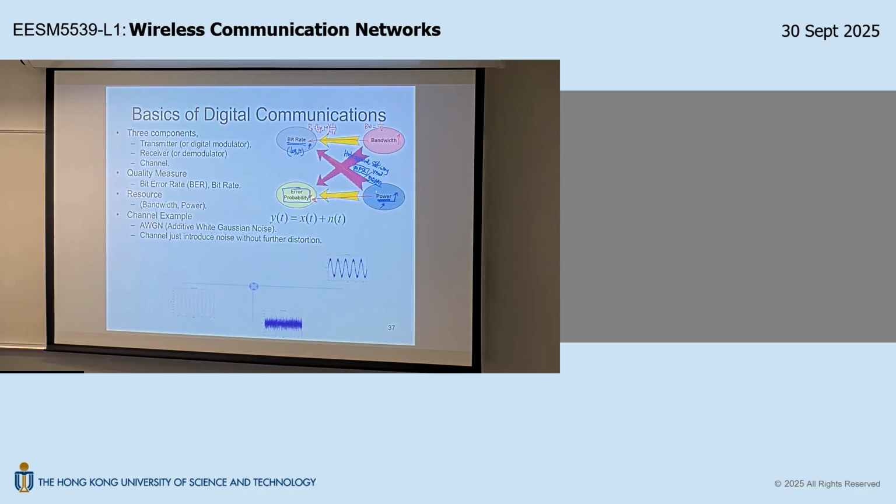So in MPSK, all these points are living in the same circle, right? So why is this called PSK? Because each point is on a two-dimensional space, right? So it naturally has 2 coordinates, 2 freedoms. But the constraint is these M points must be on the circle, right? So you start with 2 freedoms for the coordinate, but then you now have a constraint. So the remaining freedom is only one freedom, right?